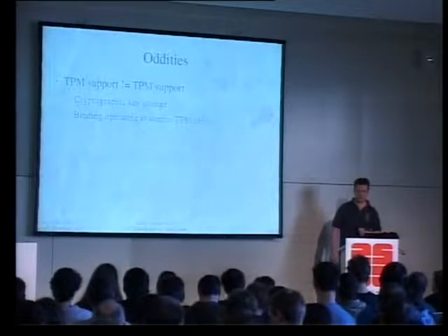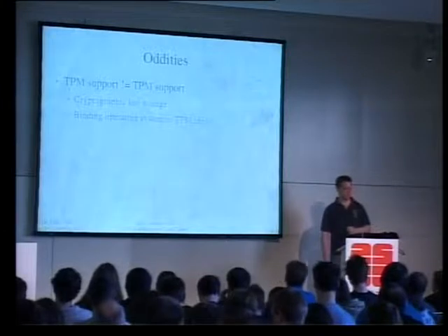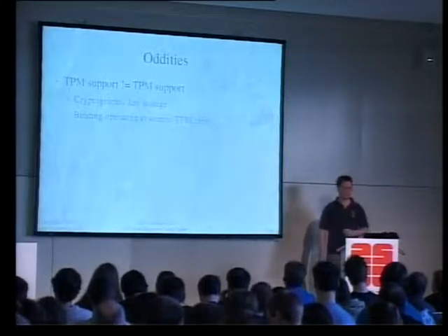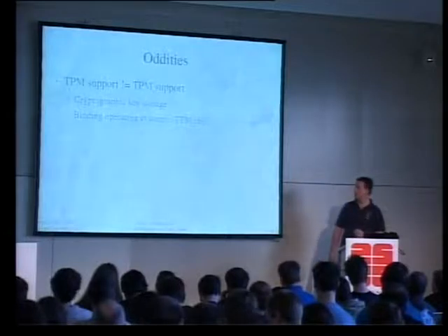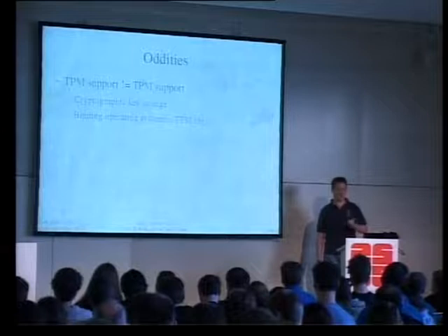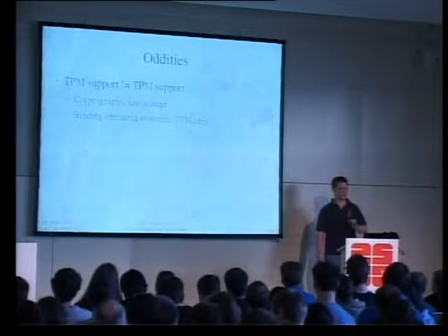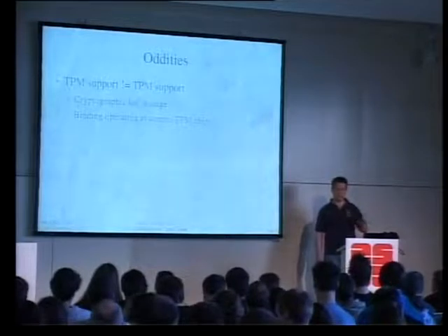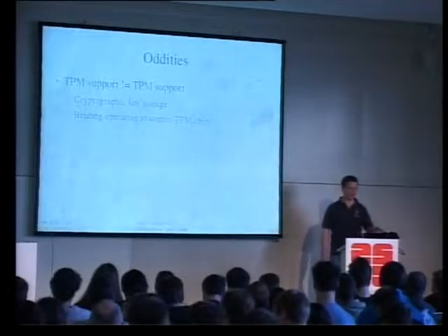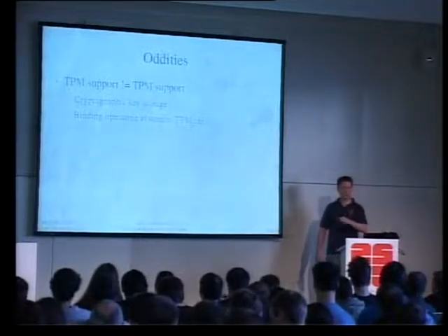We've had several vendors out there, and they all said, yeah, we have TPM support, and when you drill down, they all just sort of back off and say, well, we can work on this. And there's actually one vendor that'll implement the cryptographic key storage on the TPM chip next year. The reason why they don't have it implemented is also fairly trivial, because TPM chips are vendor-specific, proprietary devices pretty much, and you need to know what protocol to talk to each model and make of a TPM chip, and they don't want to do that.